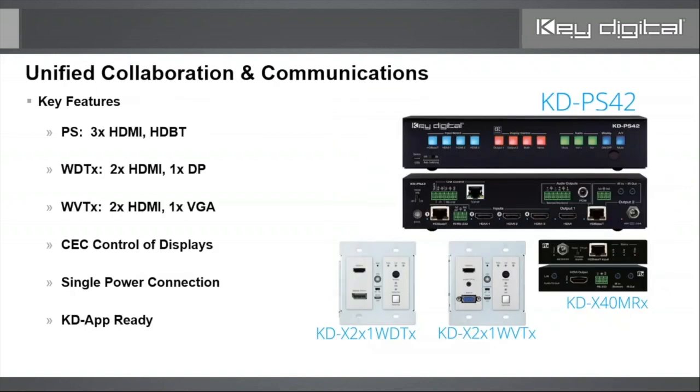Well, these presentation switchers all have CEC control, and it's built into the face of the presentation switchers. So we can control the monitor on and off, volume up, volume down over CEC. You don't need IR wiring or RS-232 with our UCC systems.